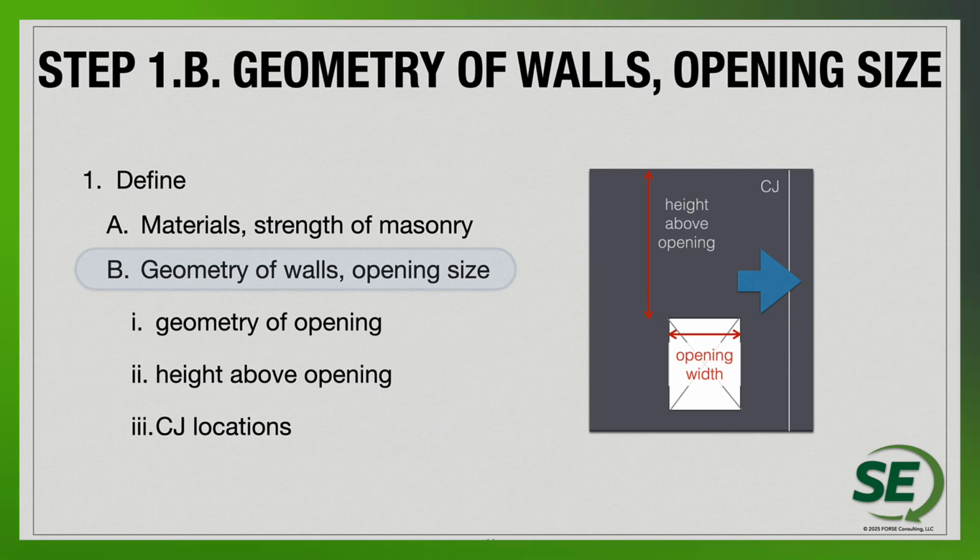into the lintel. When the control joint is going to be next to the opening, it's going to be more like a simply supported element, and it's also going to have a lot more loads that it's going to have to be designed for. So looking at control joints and where they go is going to be extremely important.